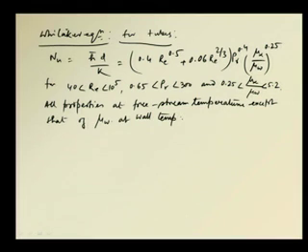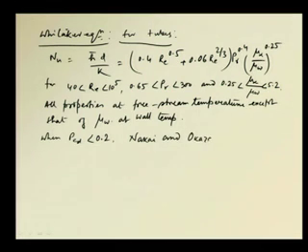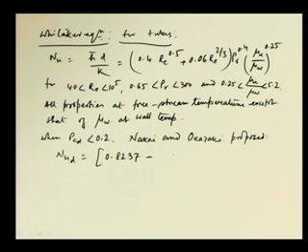So, finally, when the Peclet number based on diameter is less than 0.2, Nakai and Okazaki proposed Nusselt based on diameter equal to (0.8237 minus ln, this is interesting, Pe_D to the power half) whole to the power minus 1.